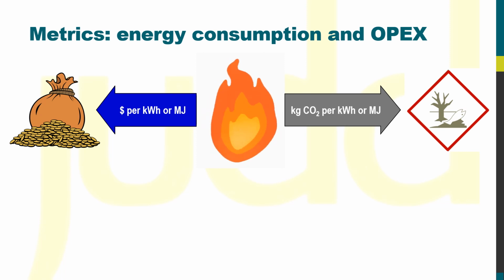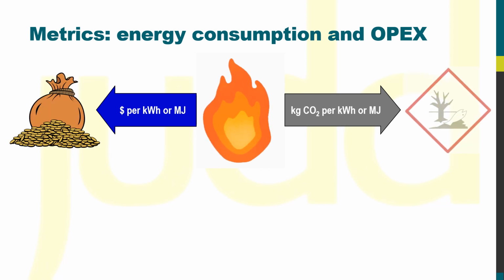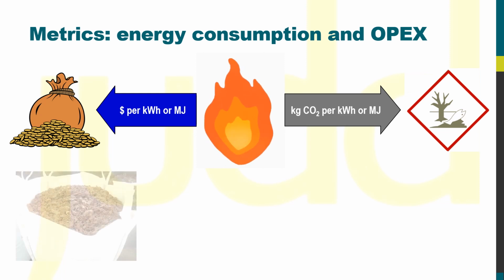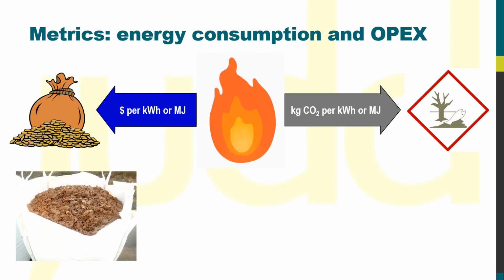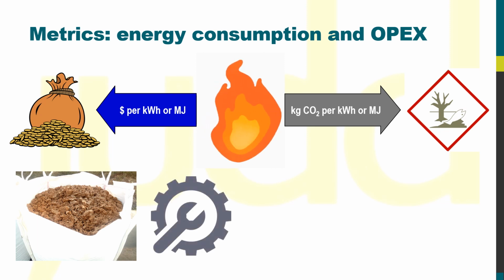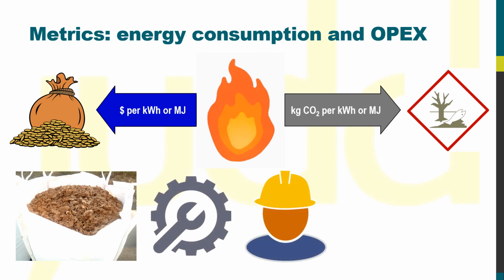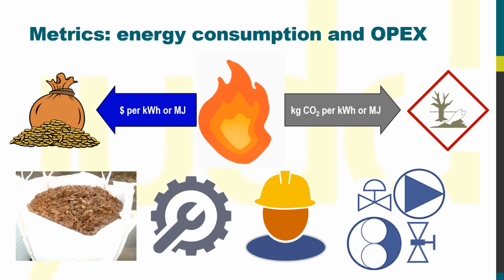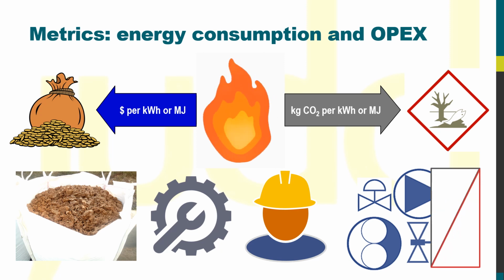Other key factors contributing to OPEX and environmental footprint are the waste generation, both volume and characteristics, as well as the ease of operation, which can impact on OPEX through staffing requirements, and critical component replacement. And for a membrane process like an MBR, the most significant critical component requiring replacement at the end of its life is, of course, the membrane.